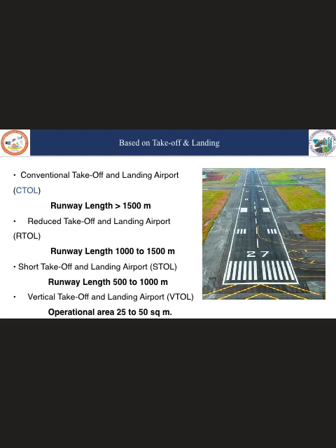Depending upon the land features or ground features at the airport site, sometimes at higher altitudes or in hill stations, it may not be possible to have a longer runway length. So depending upon the contour of the region and ground site conditions, you can choose any one of the runway lengths. As and when the restriction increases, runway length reduces, the restrictions will be more for the pilot, and he has to carefully land or take off the aircraft wherever there is a restriction on the runway.